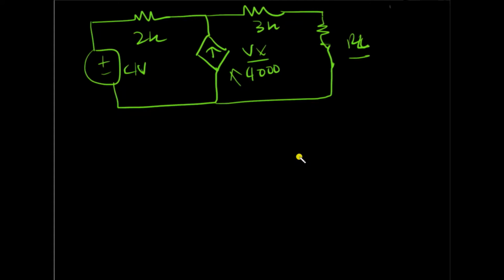In order to make concepts even more clear about the Thevenin and Norton equivalent, let's just solve this new example. You can instantly see that there is a dependent source involved, so you cannot use a simple method of finding R Thevenin. You would have to find VOC as well as ISC. So let's just start off by finding VOC.